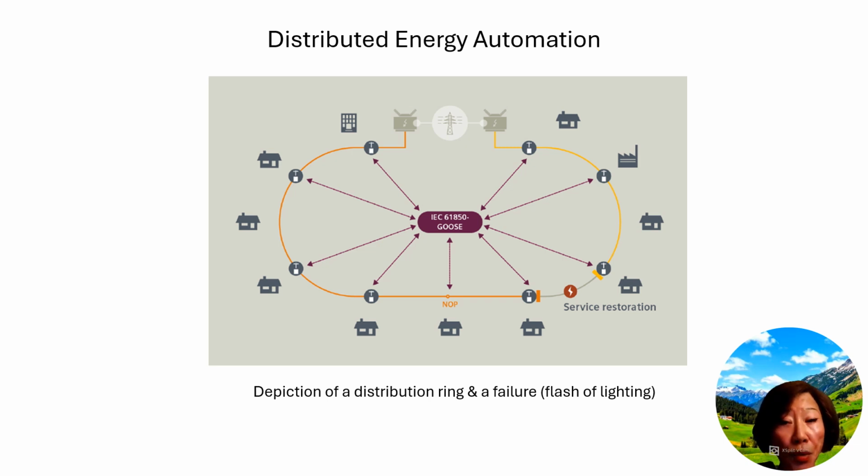These devices support the self-healing of power distribution grids with overhead lines and act as control units for reclosers and disconnectors. The system employs fully distributed, independent automated devices with the logic residing in each individual feeder automation controller located at the poles in the feeder level. Each feeder section is equipped with a controller device.